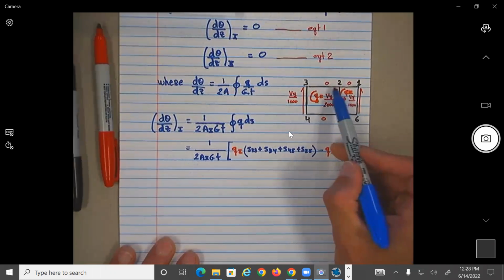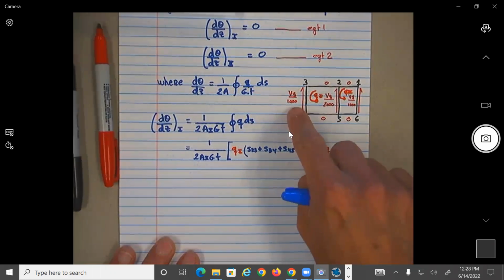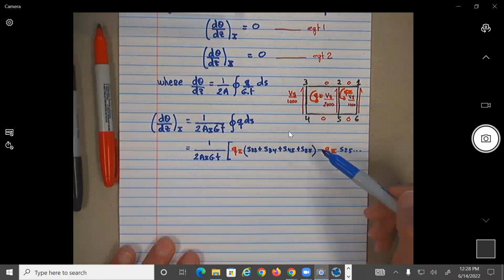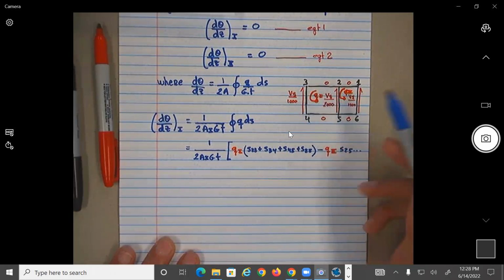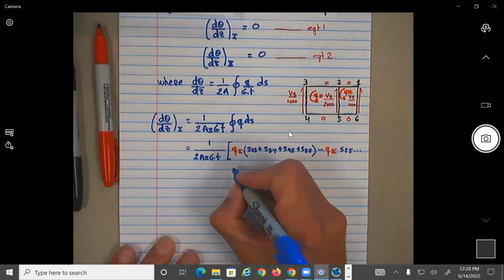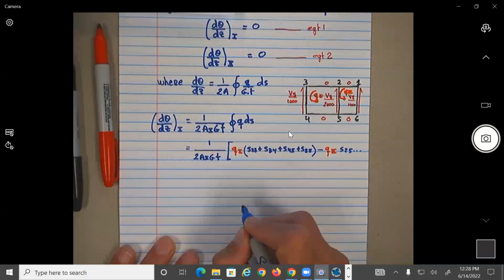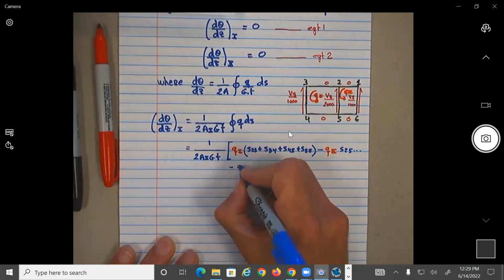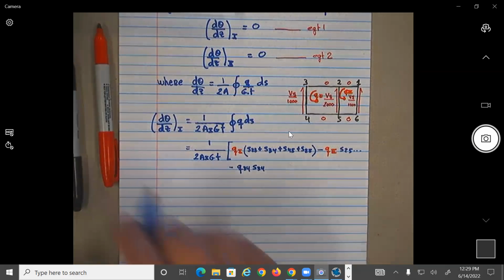So now this one is not creating anything. Now this one, be careful. You take the magnitudes as they're over here. So this one should be what? Positive or negative? To go everything counterclockwise, this one will be creating what? A negative angle of twist, no? So you should put here now minus Q34 S34, but make a note.